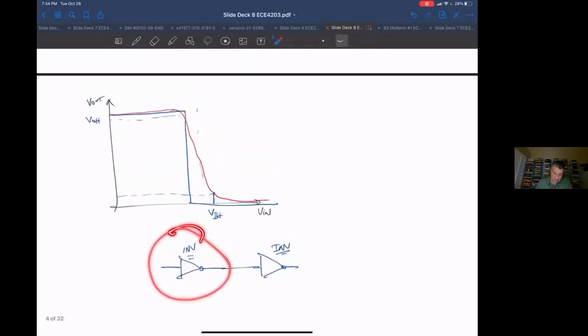So if this guy is the lowest, the worst case output high value that it's outputting, it'll be on this axis, right? This is the output axis. So its worst case will be here when the slope goes to -1. Anything beyond this is not considered a good one anymore. Okay, so that's VOH. And you want to compare that to what's accepted on its own.